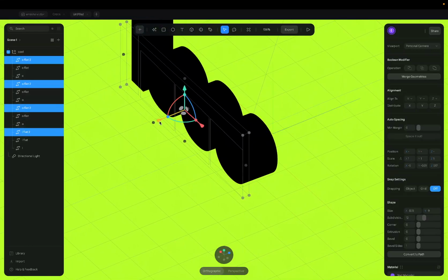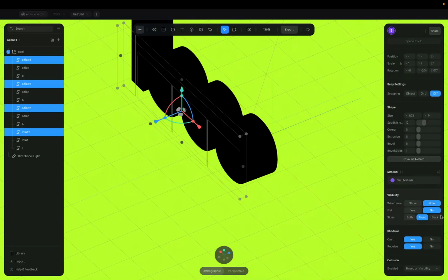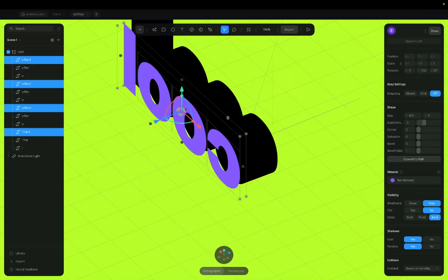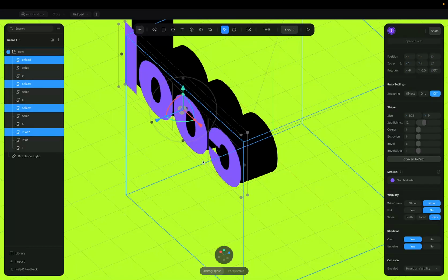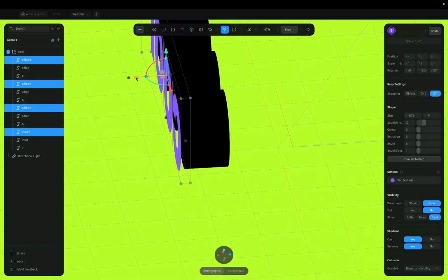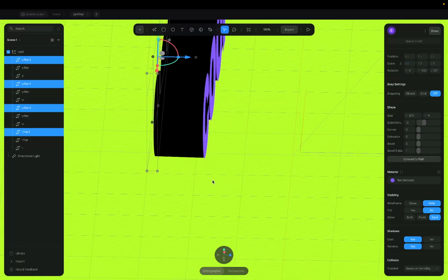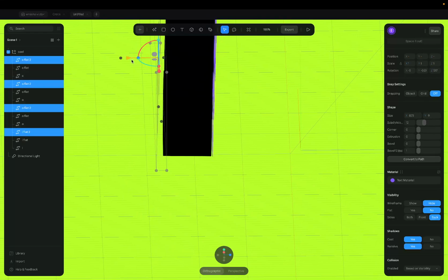Although you're not really going to see anything, because if your option here is not turned on, the back of the object may not show. So you can just come here and press the option that says back, visibility, sides, back. So make the back visible so that you can see the back of the text. Try to move your camera around and align it with the back of the text. It's not perfectly aligned because for some reason we made a mistake when it started.